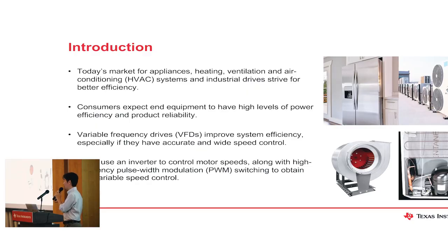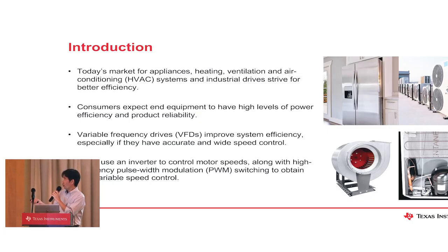But from the manufacturer, the maker, the variable frequency drive, VFD, solution is used to improve the system efficiency if they have accurate and wide speed control. And actually VFD is the system that uses the inverter to control the motor speed at the high frequency pulse width modulation switching.